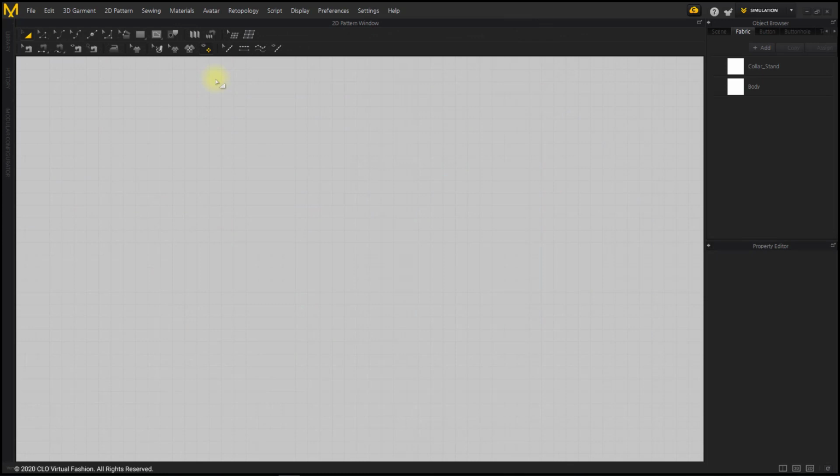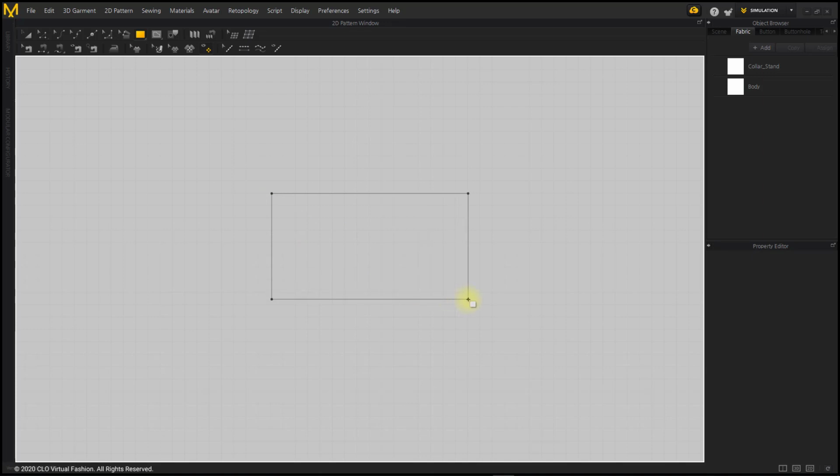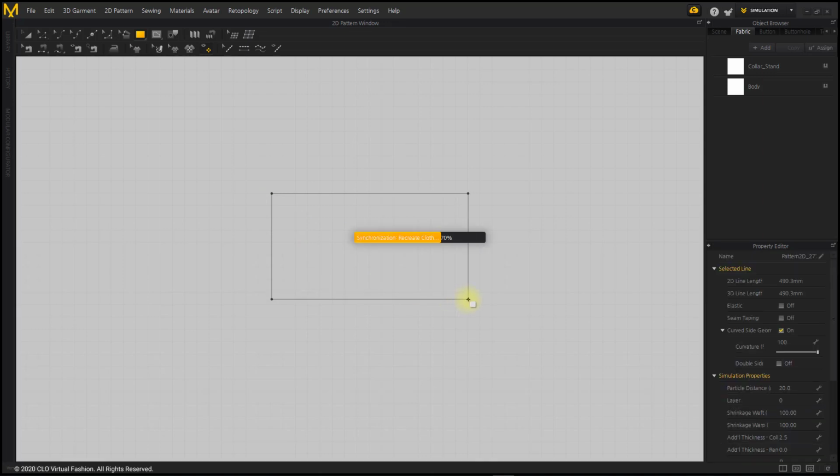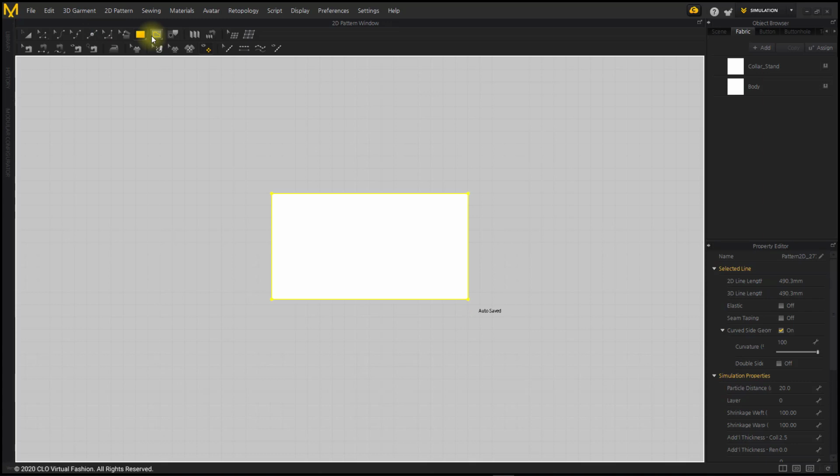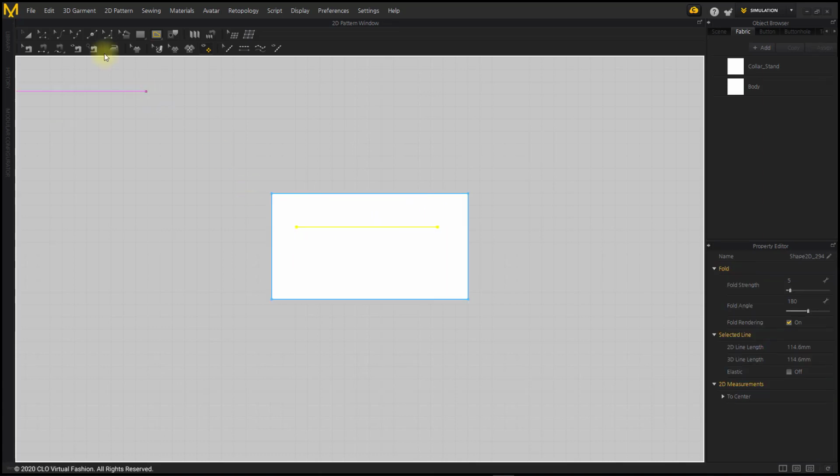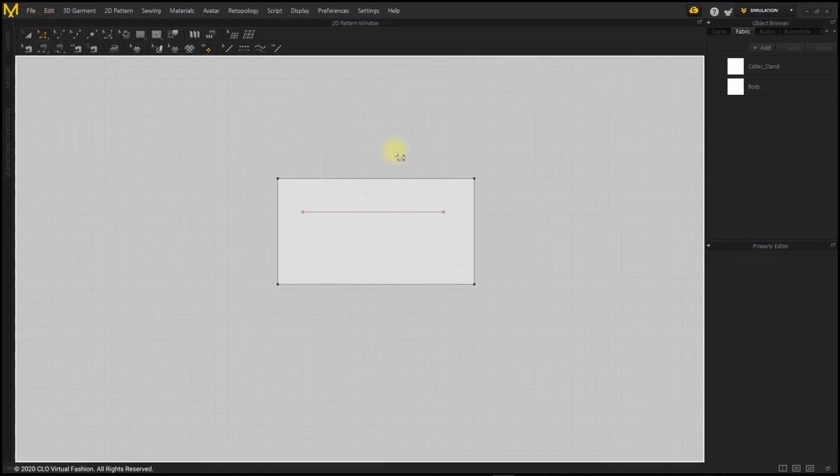Let's talk about baseline. When you load the garments from the modular configurator, or use certain features of the program, you will see a blue thin line. It is called baseline. Unlike internal line or pattern outline, it could not be selected by Transform Pattern or Edit Pattern tool. The purpose of this line is just to mark rather than using it as an object. Displays a point or internal line when the pattern is moved from the existing position.